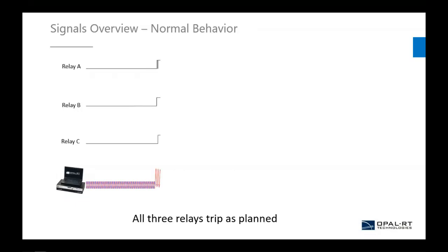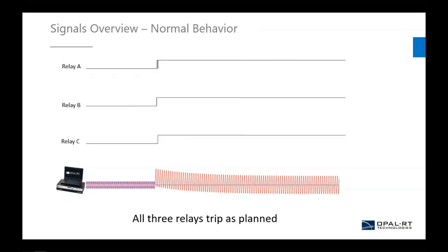We went ahead and tested these manipulations on 3 relays available on the market. We will call them A, B, and C. These relays are set as differential protection. The real-time simulator is sending 2 streams for the differential, which are sent to the relays. A power system fault will be triggered on one side of the protection so that the relays are in trip mode. This trip mode will be the base for data integrity manipulation tests because it's easier to see their effect.